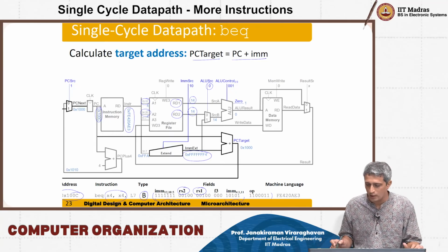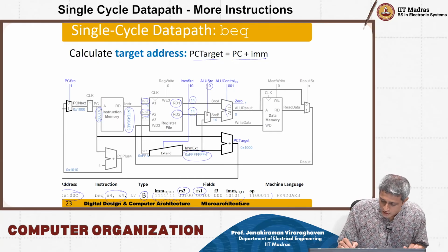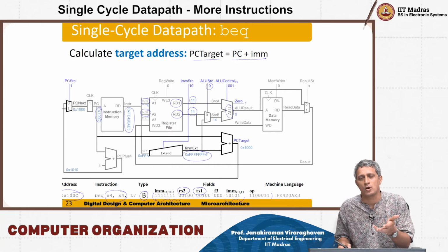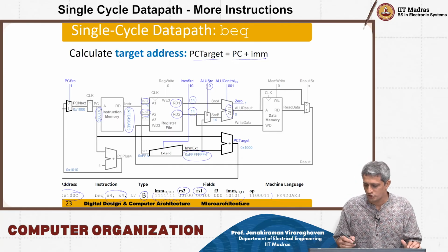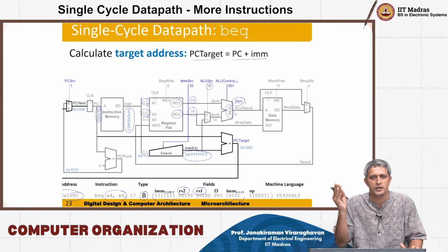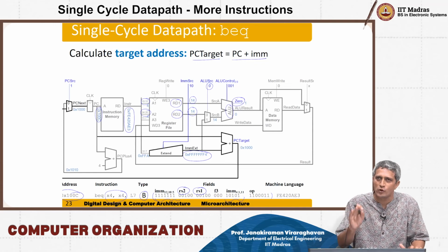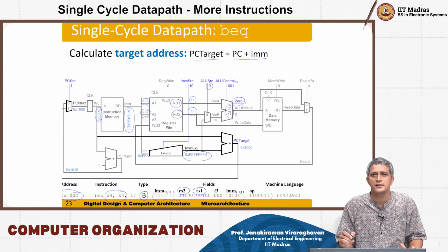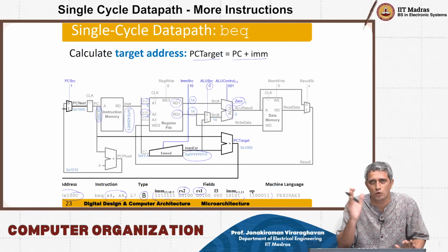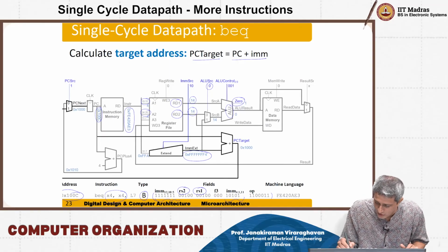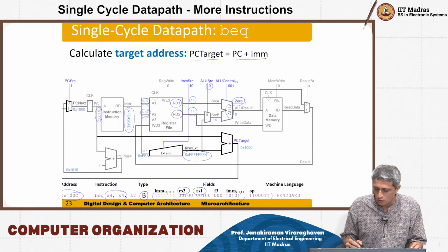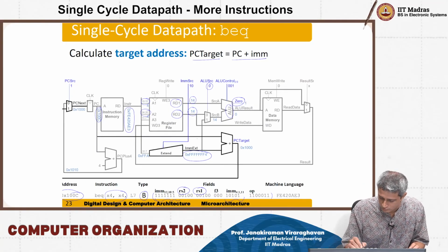So what we are doing here is, you're going to use this ALU to perform a compare operation, or a subtract operation, and there is a flag called 0. Just like we had a carry flag, 0 flag and all that in exercise 6. In RISC-V, we have only a 0 flag. After the ALU operation, if the result is 0, the 0 flag will go high. So you are going to use this 0 flag, which will obviously be 1, in order to calculate this new target address.